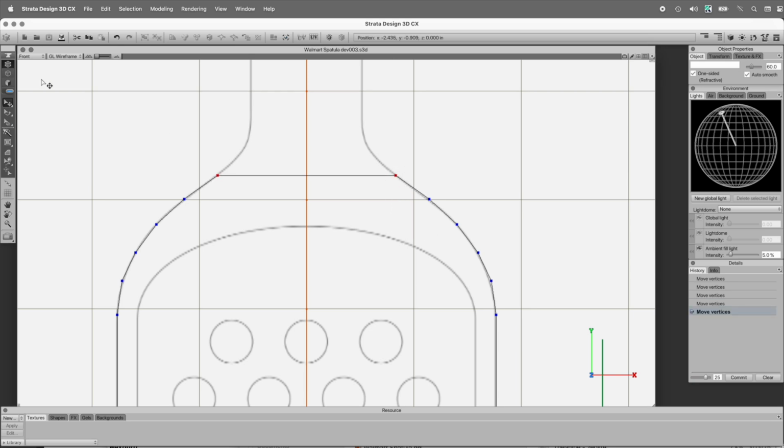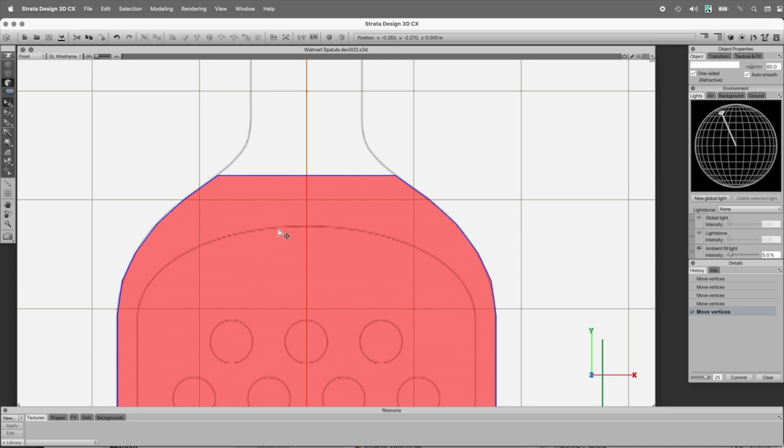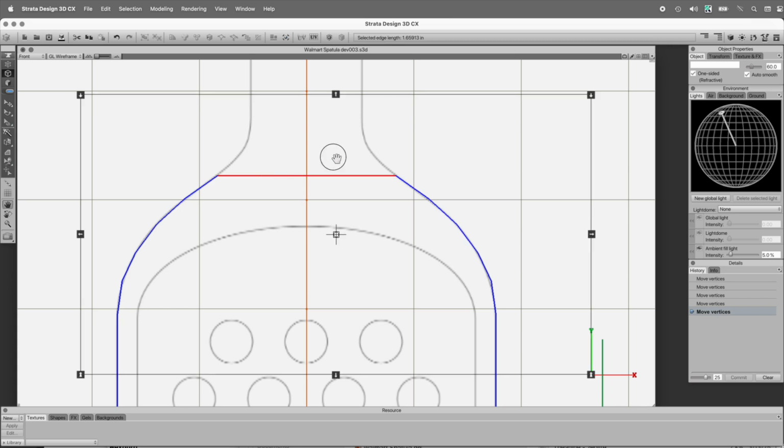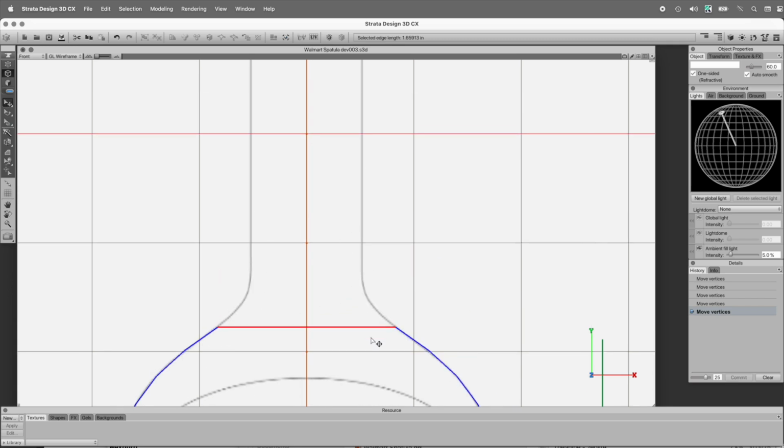So currently we have one polygon. If we switch over to polygon mode, we can see that it's an n-gon. Let's switch back over here into edge mode, and we need to kind of complete the rest of this handle part. So let's do this. Shift and C. I've already got my Y-axis constraint on, which is Shift C. It's C because that's just easier on the fingers.